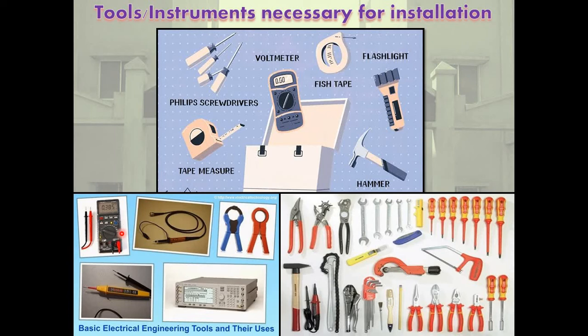Electrical hazard. An electrical hazard defines a dangerous condition. These dangerous conditions are related to energized equipment or a conductor at workplace. If a technician comes in contact with the energized equipment, then the equipment may cause injury to the technician. There is a possibility of being electrocuted or getting an arc flash, burn, thermal burn, or blast injury while assembling the components in a unit.